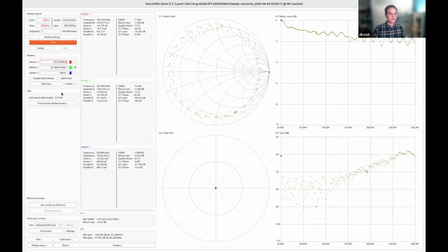About a year and a half ago I completed my PhD in RF power amplifier design. Interestingly, one of the things I didn't get to here, which maybe is the relevant part too, is how do you measure active devices? You get into a lot of situations where even this small Mini-Circuits block amplifier I have here already puts out enough power that it would damage the NanoVNA if you just drove it directly in.